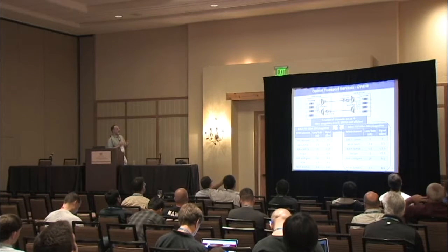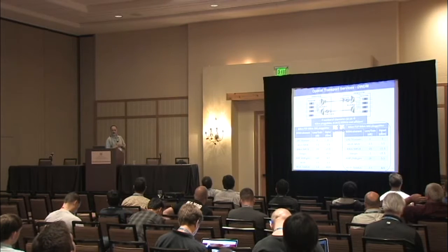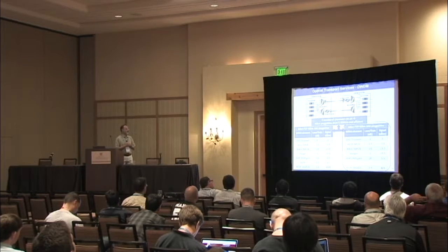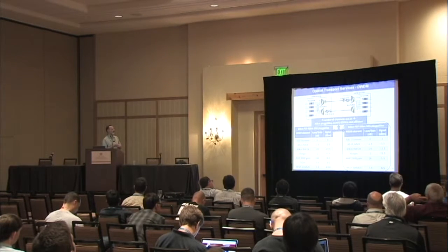So the empirical economical calculation says that if you dare to do it, and I prefer to use the 80 kilometer optics, you can use 40 kilometer pluggables, DCM and EDFA, because it's more economical.